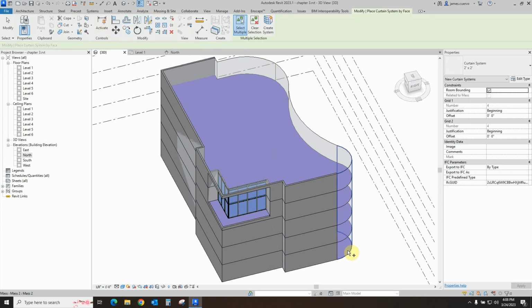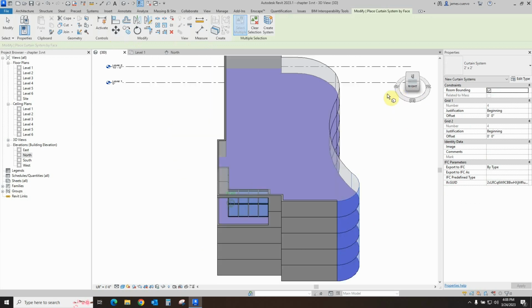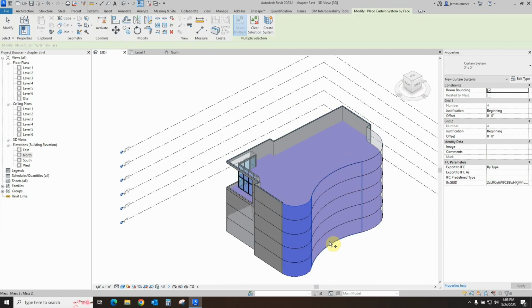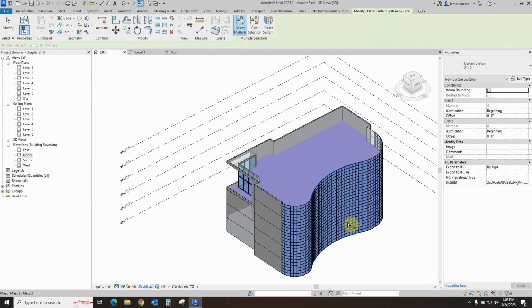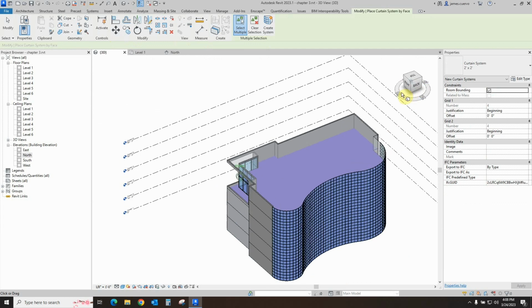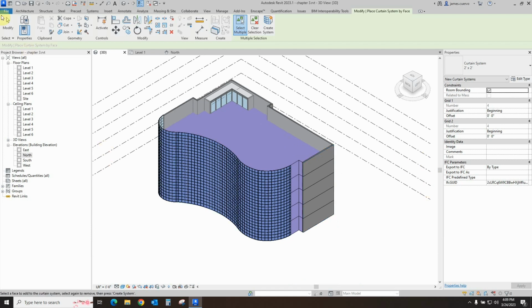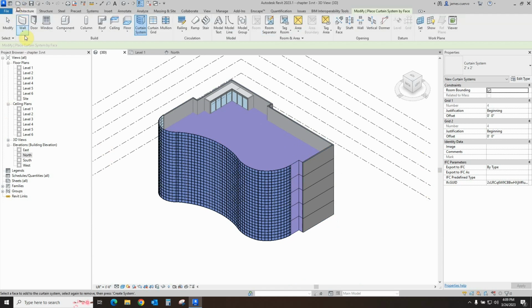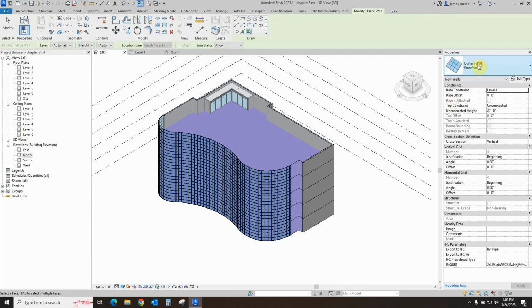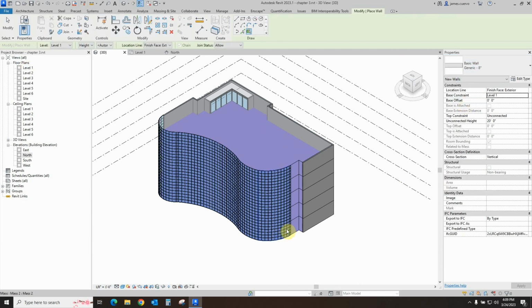I'll go ahead and define this section in here to be one. And I'll continue to select faces. And once I have all of my faces selected, all I have to do is say create. And the software will generate all of the mathematical equations and mathematical items that it has to do in order to define the item the way I want it. I see that I missed two other walls here. Let's go back to architecture. Select by face, come back and reselect the one that we want, which is the 8-inch generic, because these are all generic walls, and there we are.